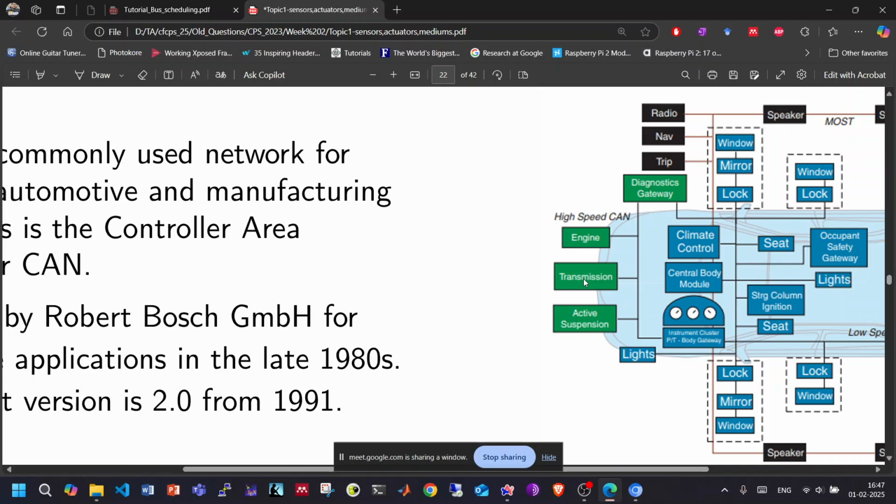I understand your question. So yeah, you have to design the system like that. The signal that is most important, the signal that is given the least ID value, should be the most important signal. Usually such kind of signals have the highest frequency. Now consider engine or transmission, it depends on how many control units are using the data.